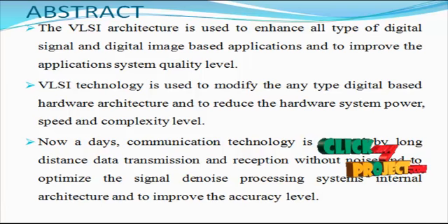For ordinary compensation, a 1/3 octave filter bank can be combined with both NAL1 and NAL2 prescription formulas. Over the past 15 years, many studies presented various effective filter length designs with different structures for digital hearing aids. Generally speaking, it's divided into two strategies. One is the uniform filtering bank and another is the non-uniform filtering bank.